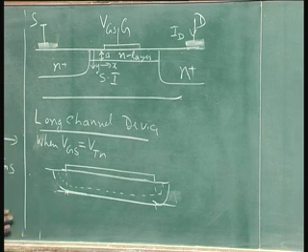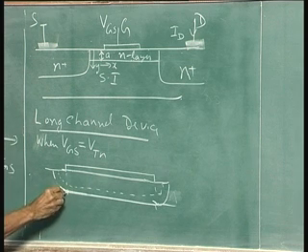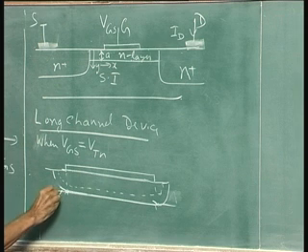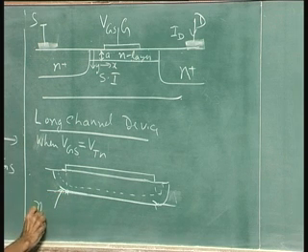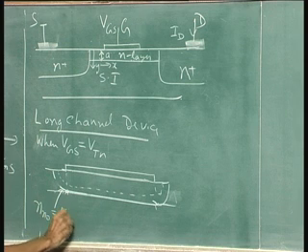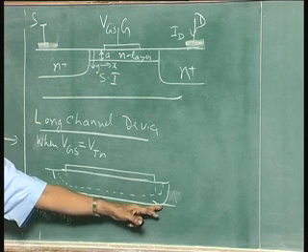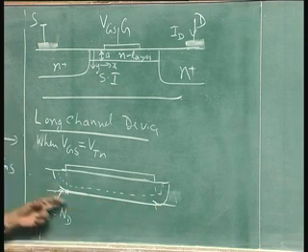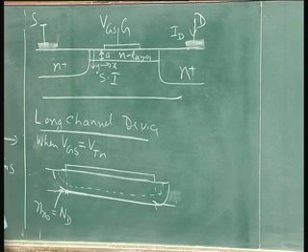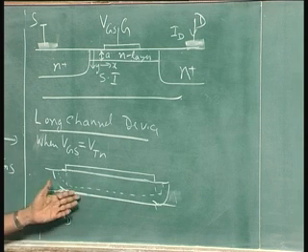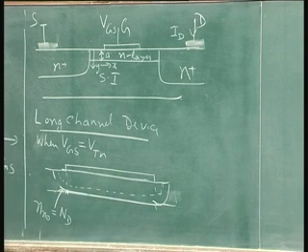The carrier concentration at this edge here is N 0, if I want to call it, that is equal to doping. Okay. What is the carrier concentration here? Same. So, if I do not apply any voltage, there is definitely no current, neither concentration gradient nor electric field.